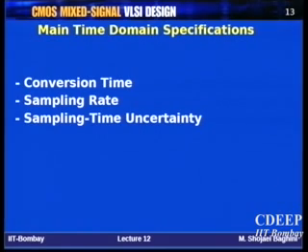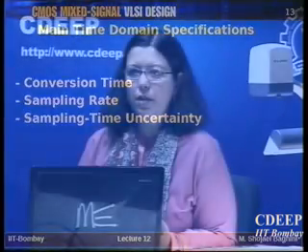If you apply a signal, suppose a sine wave, and you have one sample of this sine wave, from the time this sample is already stored on the sample and hold, from the time this sample is applied to the ADC till you get the final code corresponding to this sample at the output of the ADC, that is the conversion time, right? So it is obvious, of course.